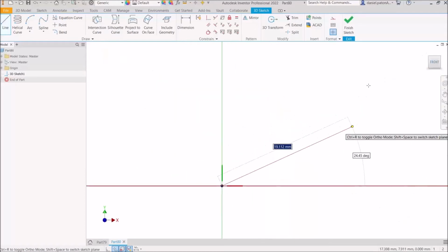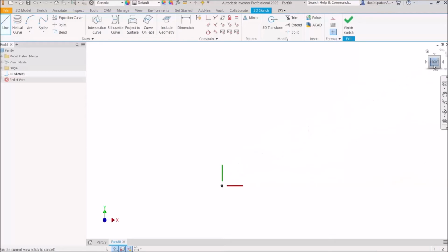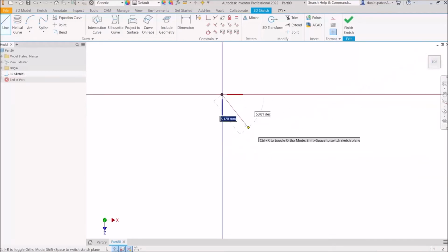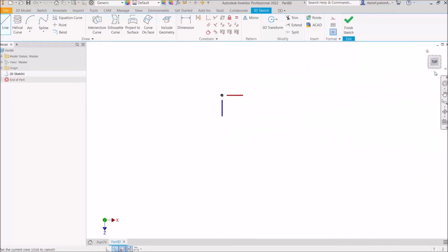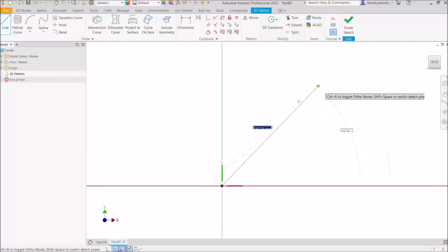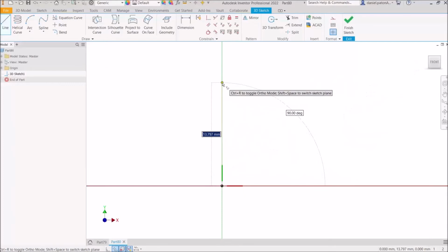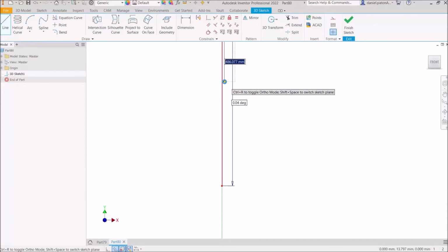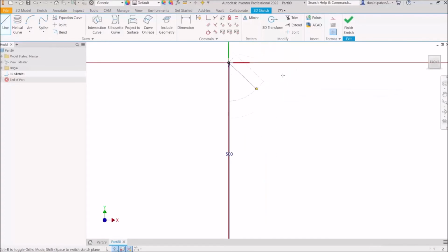Okay. So to prevent that, you can use the view cube once again to specify where you actually want to draw. If you're drawing in the XY or the XZ or the YZ work planes, simply by selecting the correct view. And we can just go and draw in the sizes that we want. Let's say we want to make this 500. Come across by 500.